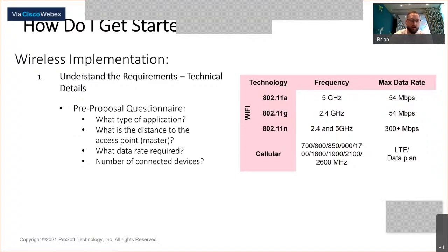Then we can look at the data rates or the packet rates that are required. Wireless Ethernet is a half duplex system, which means only one device can communicate at a time, and the radios leverage a protocol to detect the usage in the channel to determine when it's safe to communicate. That essentially means the entire system needs to be engineered so the only data that's being sent wirelessly is that essential data that is required for control, that's required for safety, that's required for diagnostics in your application.